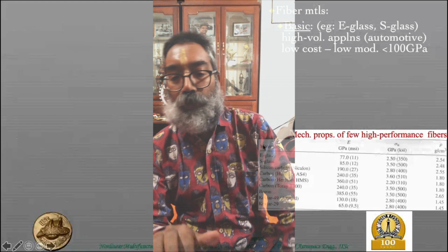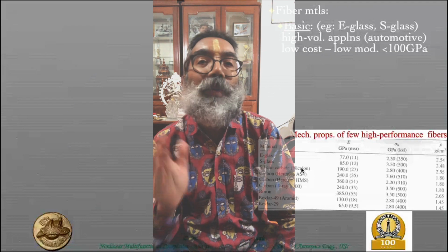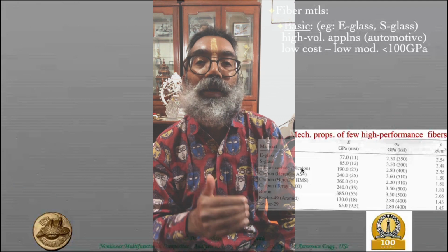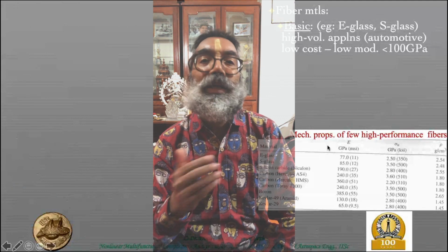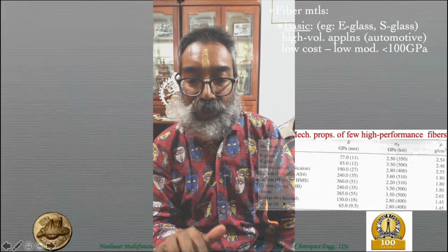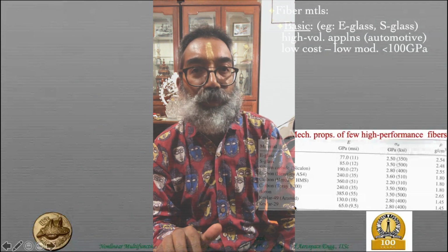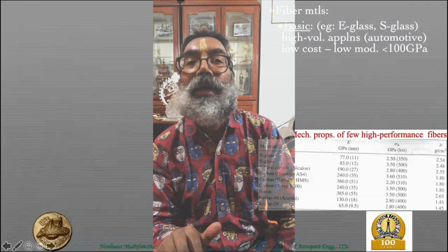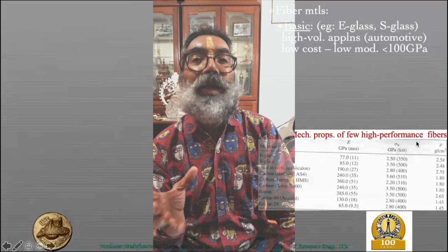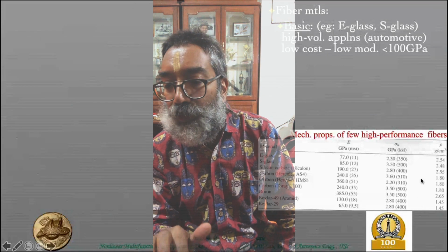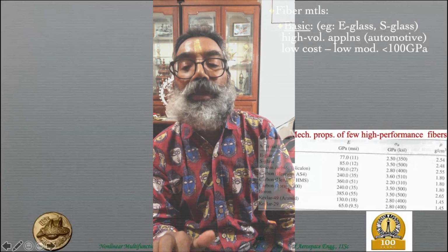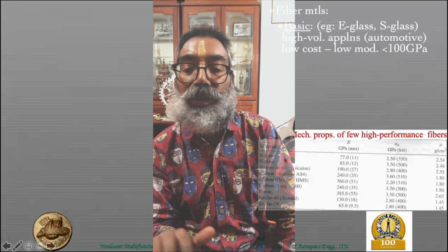Yeah. See, all of these, it depends on the material that is involved. You just go back to the original classification of what they were, whether it is a polymer, a ceramic, or a metal. For example, Kevlar is an Aramid fiber, so it has a certain level of ductility, which is what enables its higher energy absorption because of the ductile deformation. One more important property that I missed giving over here is the failure strain, because that is another critical property which determines the ductility.